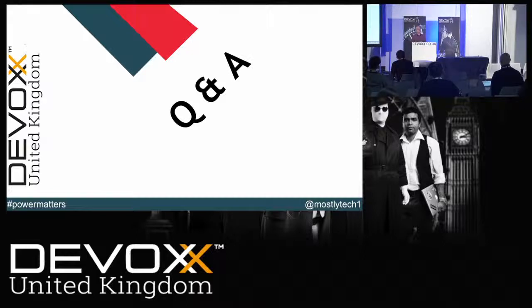If you Google sensor batching and wearables, I think you'll find some good information. The bottom line is you're going to wait until the CPU is awake. So you're going to batch the data. In most cases, like with a sleep app, it's looking at the gyroscope, and then you're waiting for the processor to be awake. And when it is awake, you say, "Oh, by the way, I've got some data."